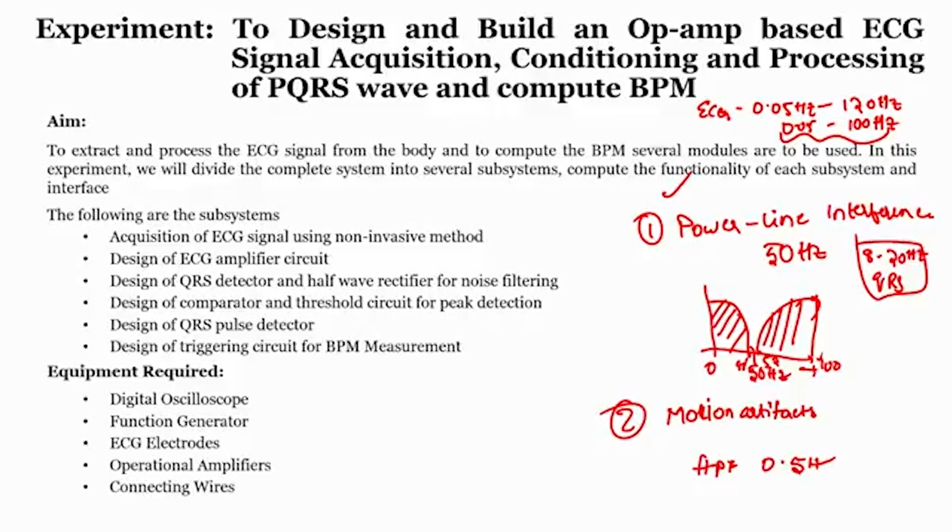And we already saw that the higher the order of the filter, the more op amps and components, the more complex the system, and the cost will also be higher. Since it is not so feasible in our laboratory, what we do is restrict ourselves to either a first order or second order filter, so that the roll off factor, compared to first order, will be higher for second order filters. So, it will always have a proper cutoff. We will also have a look into that too.